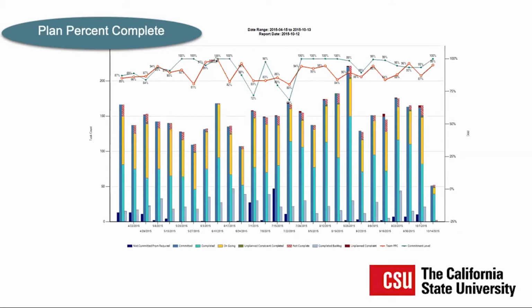I had a sidebar conversation with the builder and said, well, you know what that means? They said, well, no. I said, these foremen have figured out that they're going to be measured, and so they're putting buffer into their schedule so they can hit 100% every week. You've probably lost the opportunity to really gain schedule if they gave you the realistic durations that were necessary for the job. That led to some interesting conversations on the project.